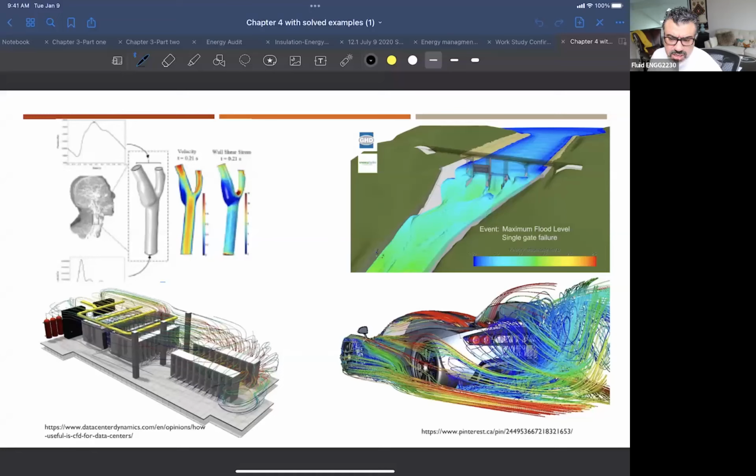Computational fluid dynamics is a topic by itself, but it is basically converting the momentum and energy equations into digits and numbers on the computer, so you can calculate those numbers. By doing this, we have to divide the whole fluid domain into very small control volumes, with sizes approaching zero. Of course, different applications will require different sizes.